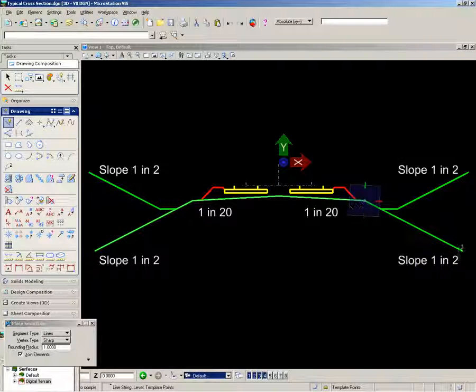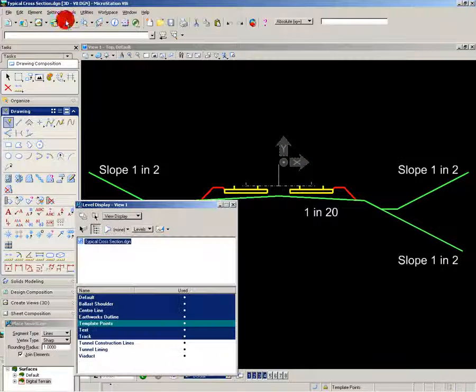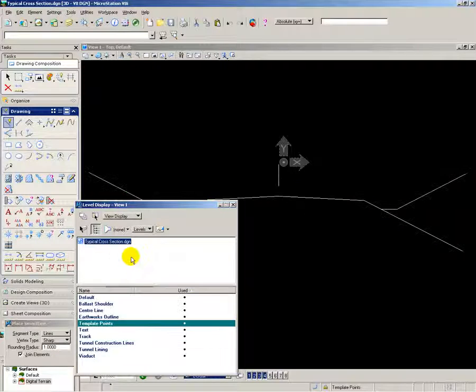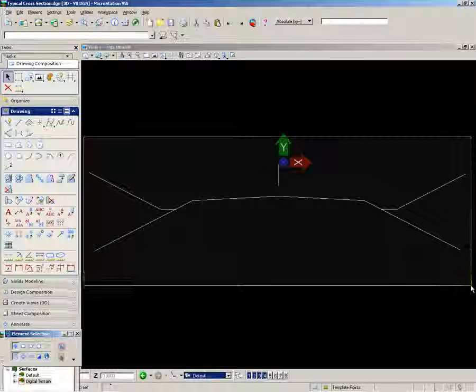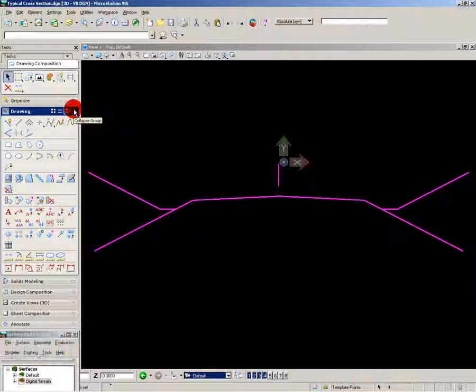And this process is repeated until all the required points have been gathered up. The final smart line I add indicates where the origin or center line of the template should be. Now turning off the scale drawing, I am left only with the key points shown on the screen. Now I want to import those key points into a Bentley Railtrack template.